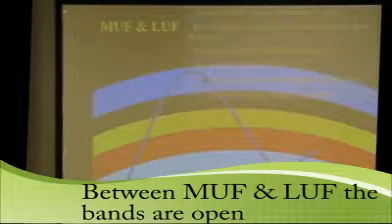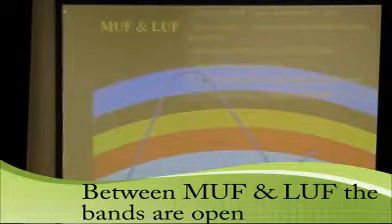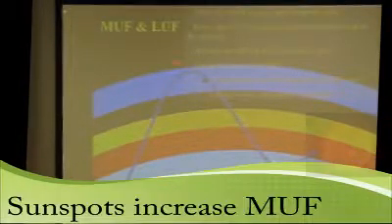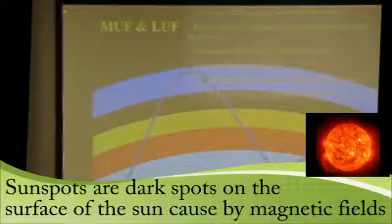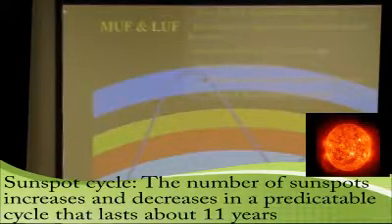Between the maximum usable frequency and the lowest usable frequency, the band is open. So essentially that's when you can talk long ways away. Sunspots increase the maximum usable frequency. That's why we're always interested in sunspots. We've had a pretty rough 11 or 12 years recently. We've had lower sunspots than, in fact, we've had some historically low.